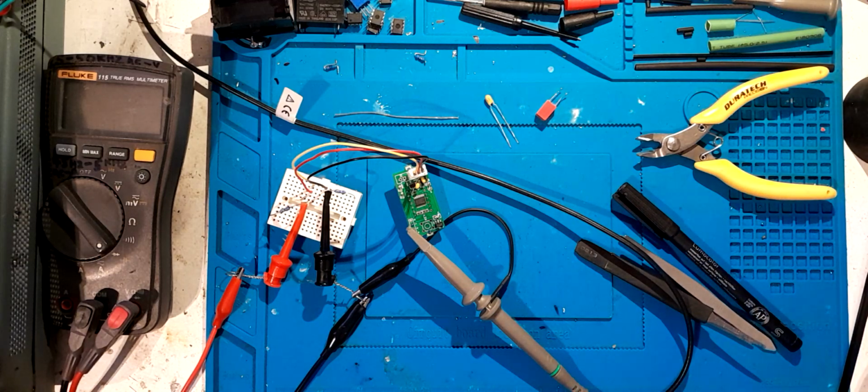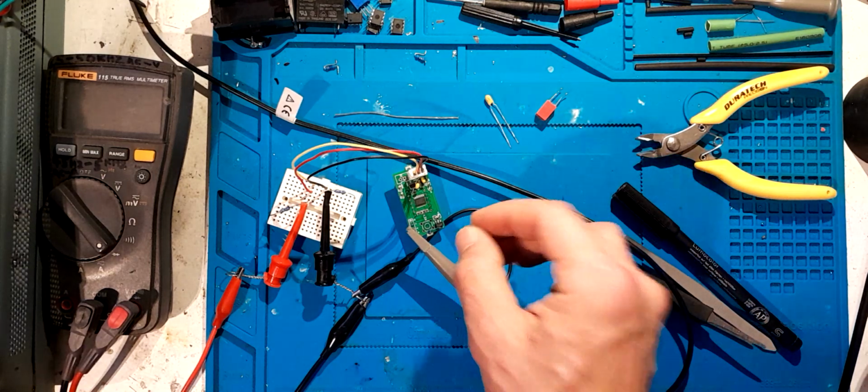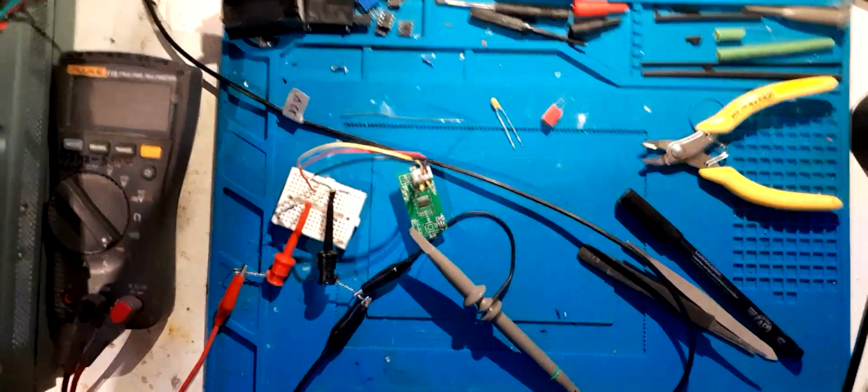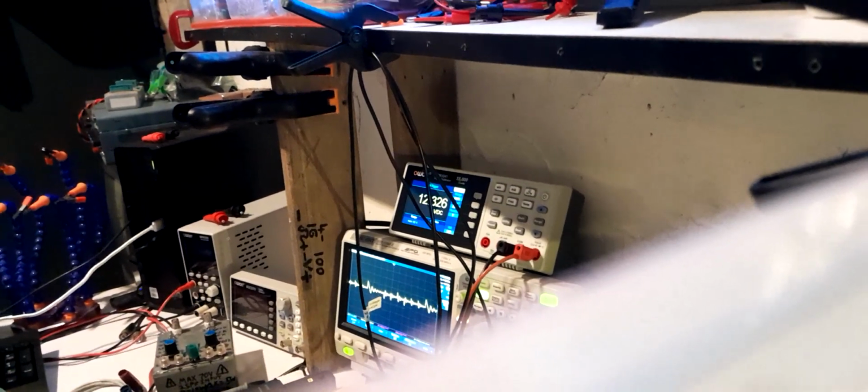I'm going to find the same type with the same frequency response, 10 microfarad ones. And I'm just going to make a sandwich 3 or 4 high to effectively make this ripple smaller. And I'll just show you guys quickly what happens when I stick this tantalum capacitor over the rail.